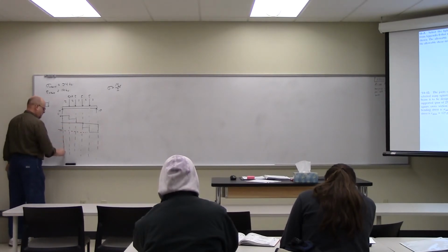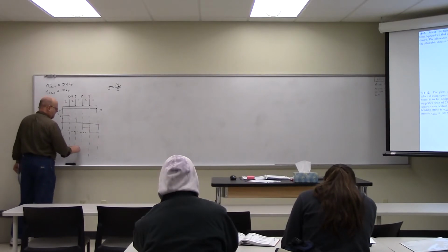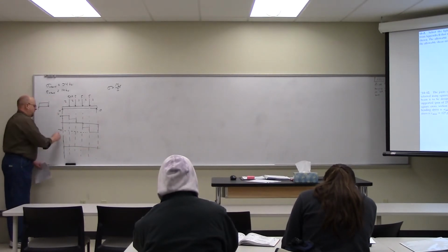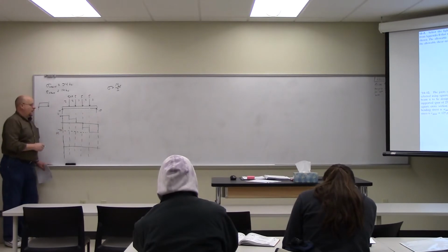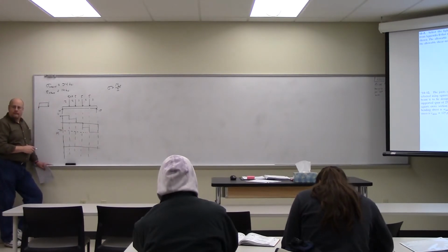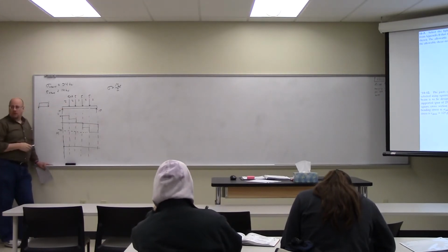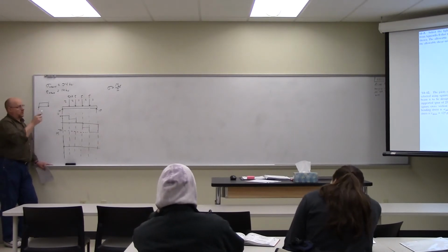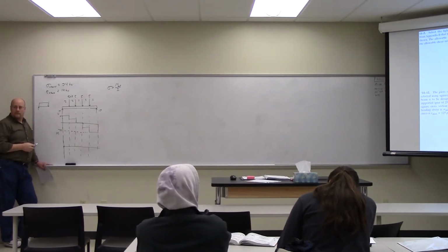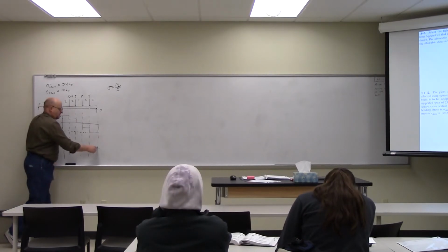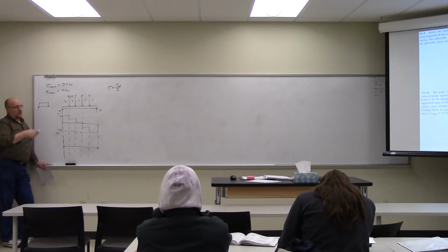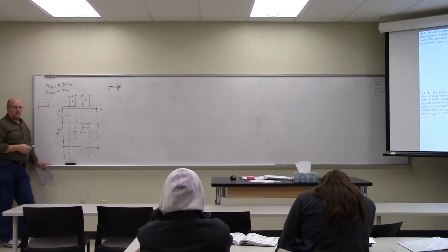Now let's do the moment. What's the moment on the left? Where am I going to start on the left side? So you start at 0. Right, it's a pin. It can't hold a moment. So it can't be a moment on the left. What about the moment on the right? 0. Also going to be 0, because again there's no moment, it's just a roller.